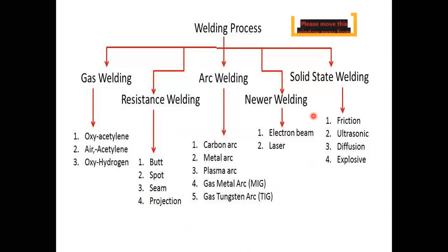Generally arc welding needs some electric power, and solid state welding also needs some electric power. But thermit welding needs no electricity, because on a railway track you never get electricity applicable for normal use, since electric traction is not available everywhere.